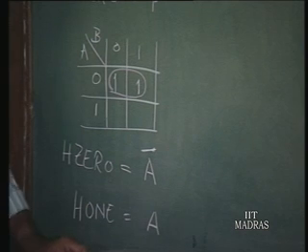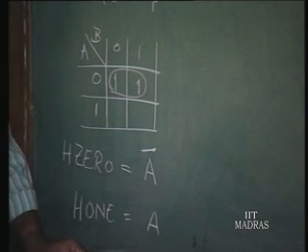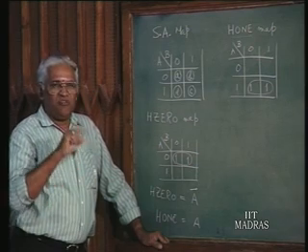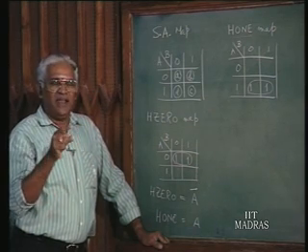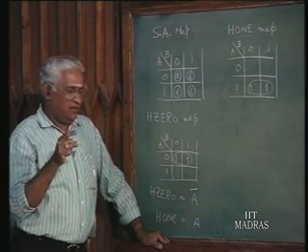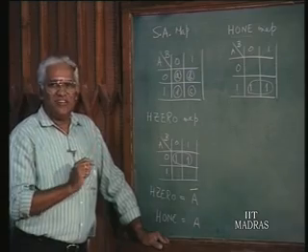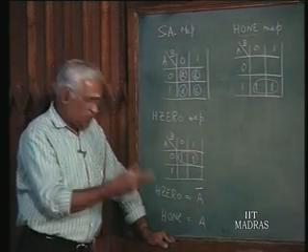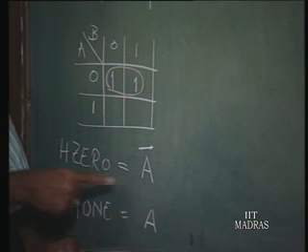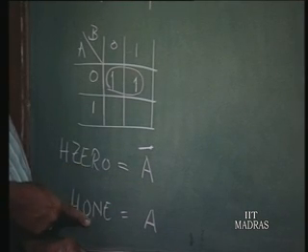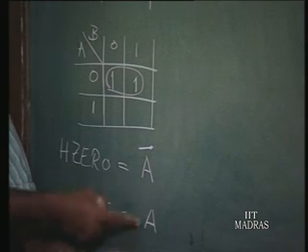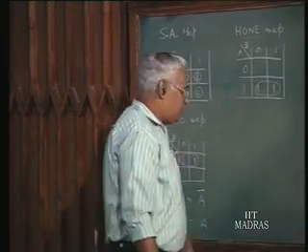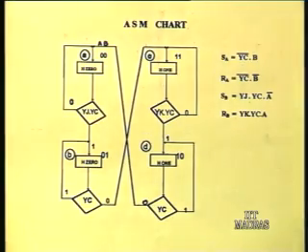And recall what we were talking about master slave flip flop. We said there is one memory element which will follow the inputs and another memory element which will be following the internal state, and that is the one which will generate the output. Now, we find the outputs H0 and H1 depend on the state of A. In other words, let us just mark it on this one.